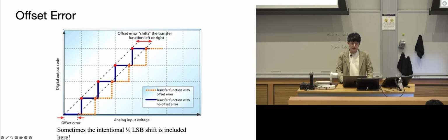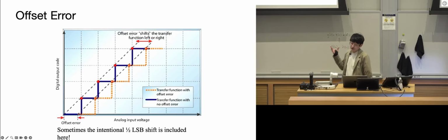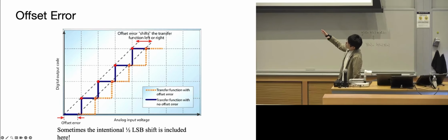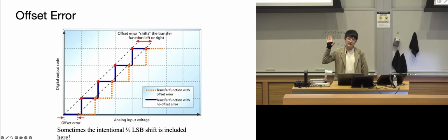We also have what they call offset errors. This is in a DAC. It is essentially the deviation of the actual output value from the expected output voltage value. For example, the digital value is 0, and depending on how you shift the actual output voltage, you might have that value correspond to 0 or a small voltage number.